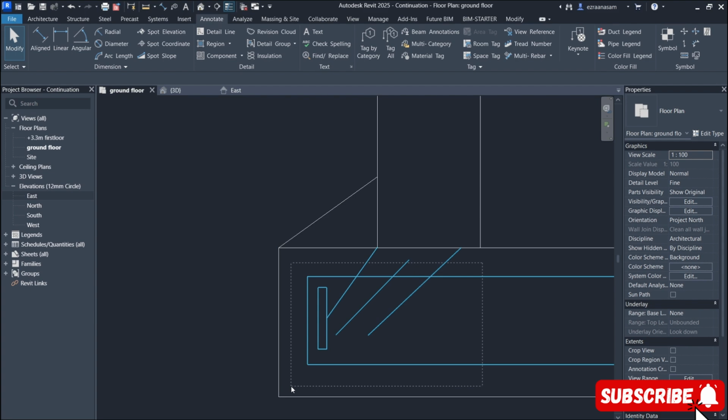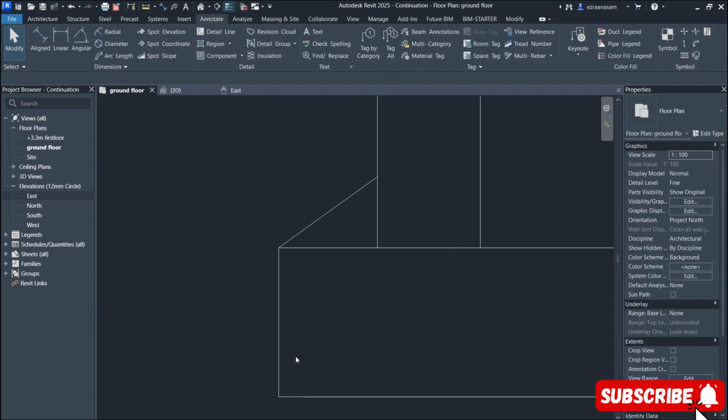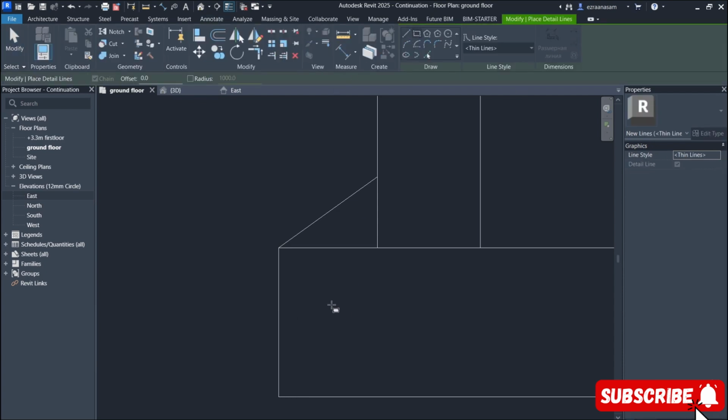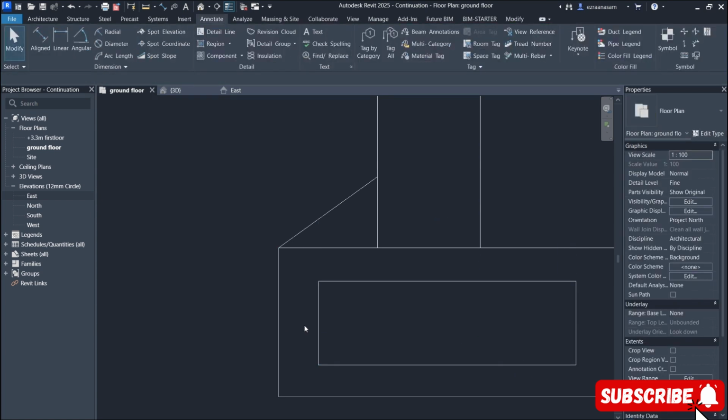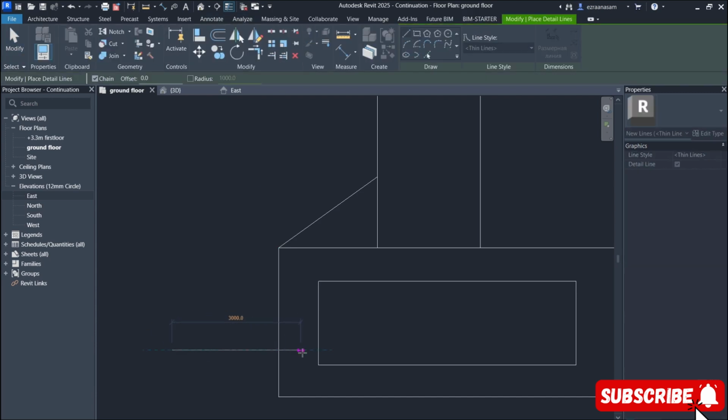There's another reason that I want to explain. The other reason is that when you have a foundation cover, we try to put our foundation cover a bit, we're not using, let's say, 25. We can decide to use 40, for example, or 35. The reason is to avoid water or any reaction coming from the ground, because this is going to be beneath the ground, like below. So it means that what?